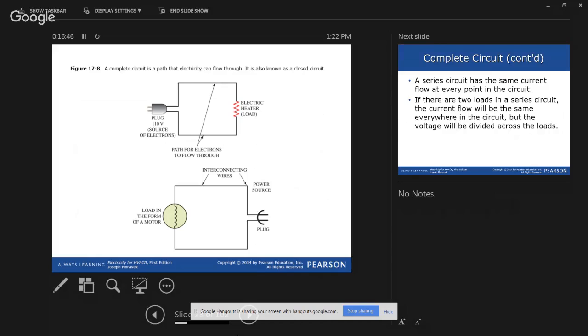Here it is, fellas. Complete circuit right there. So we have the 120 volt scenario here where we have the hot, your 120 volt wire, coming through, going through the load of your heater and returning back to, in this case, the wall outlet on the neutral.